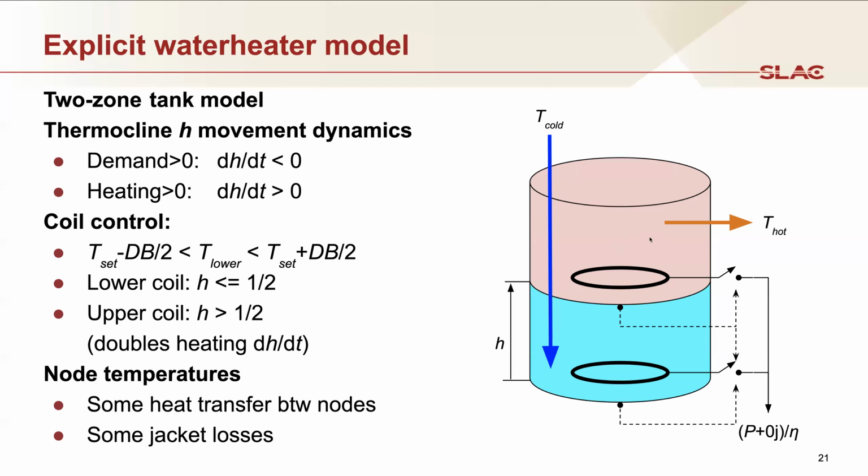Over time, there are slow losses in the mixing of the temperature, but it's quite slow, and it's because of heat transfer between the 2 layers and through the shell of the tank. And then, of course, there are heat losses, and those losses, for cooling, are quite slow, but they give rise to the standby load that you typically see on a water heater if you just let it sit without any demand. So what drives the water heater model is the water consumption, and that is essentially driven from the same load shape as the water heater demand.